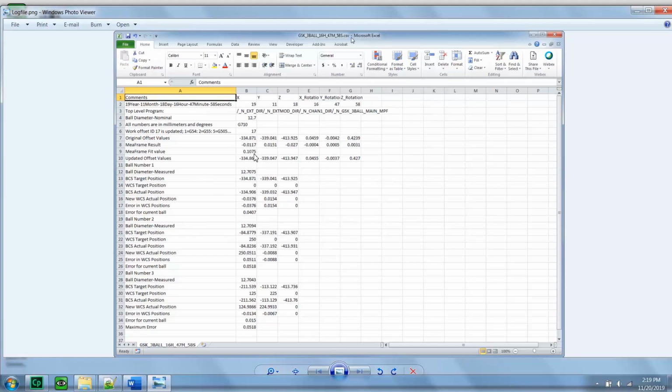So for gantry machines where you have 2 rotaries on the head, generally speaking, that means the table on the floor or the concrete. For machines with a tilt-rotate table, like I have in my videos, the BCS is generally going to have the 000 at the origin of the table. And if we pulled out a marker and drew on the table and we drew X, Y, Z, as that table spins around, the BCS is spinning around with it.